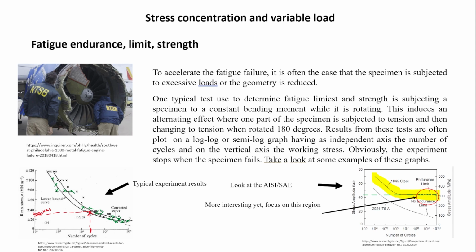In the other case, where you have materials that don't follow the same shape, like in this one over here, and let me change the marker to draw that one. Then what you say is that for the yellow case, the first one, there is an endurance limit, and for the other case, the green one, there is not an endurance limit.